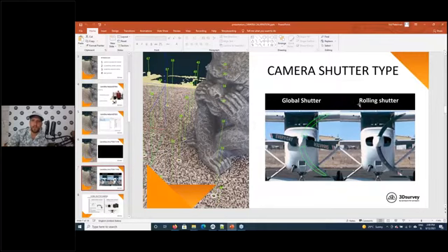Most cameras that have a CMOS sensor inside, and that's most cameras we have, like cameras in our phones and handheld cameras, read out the sensor a line at a time. First line is read, then second, third, fourth, fifth, sixth. So for example, if you take a picture of a rotating propeller like we have here, you would get this kind of distortion because the different vertical parts of the image were recorded at different times.